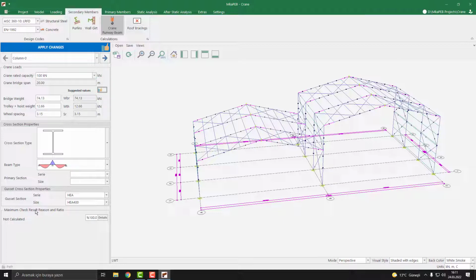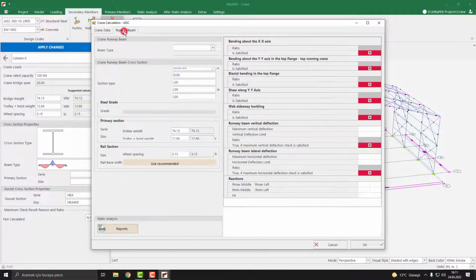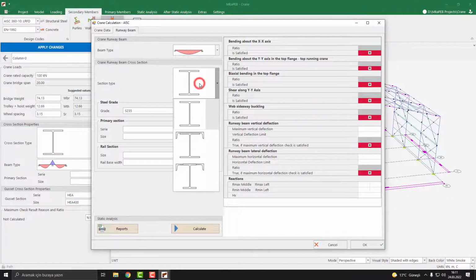Then our maximum check result ratio is not calculated. To calculate this, click Details button. You need to fill these parameters, or you can use the recommended values. I click the runway beam, and you need to select the beam type, single or continuous. I select single. The section type is...